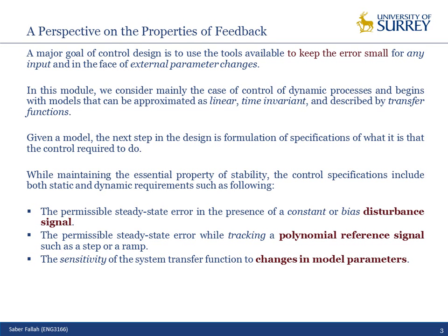For example, you design a controller for the ABS, active anti-lock braking system, based on the properties of the tire. But the tire is new, and the properties that you have are for the new tire. After 1 or 2 years, the tire will get old and it will lose some properties. So as a very simple case, the stiffness of the tire will change.